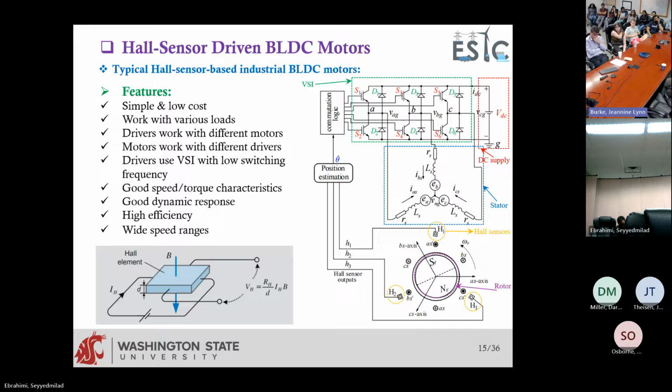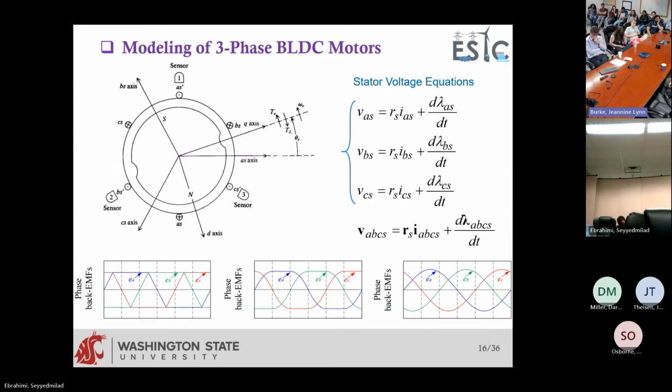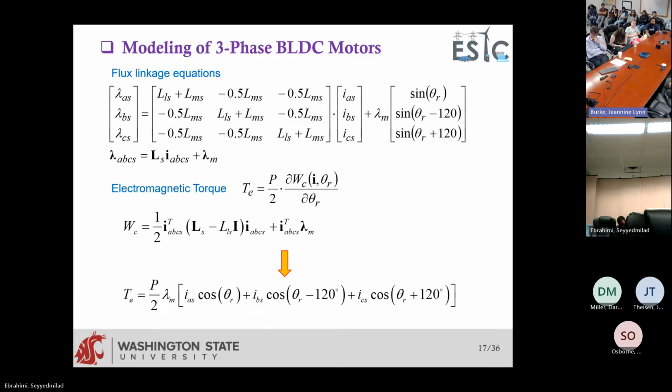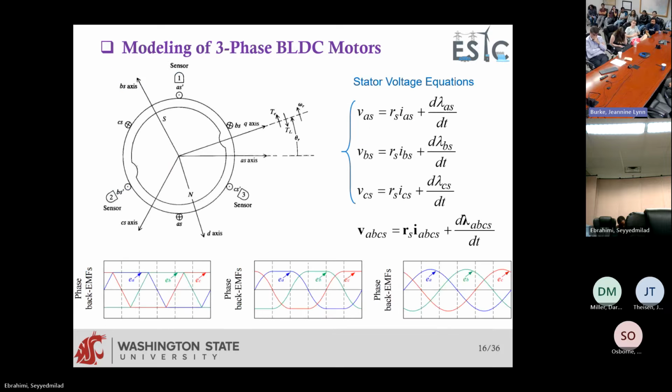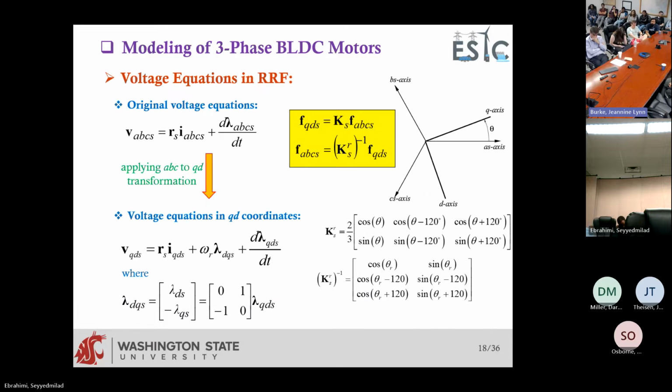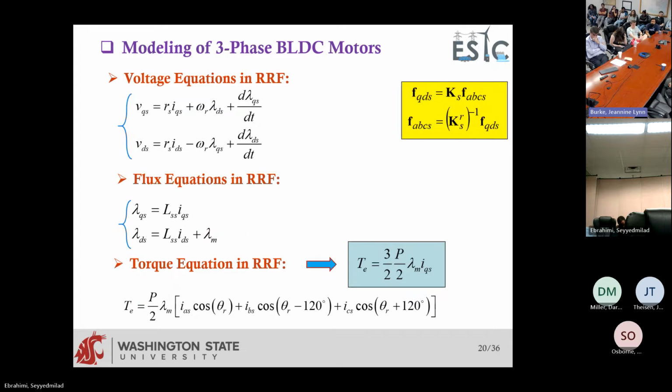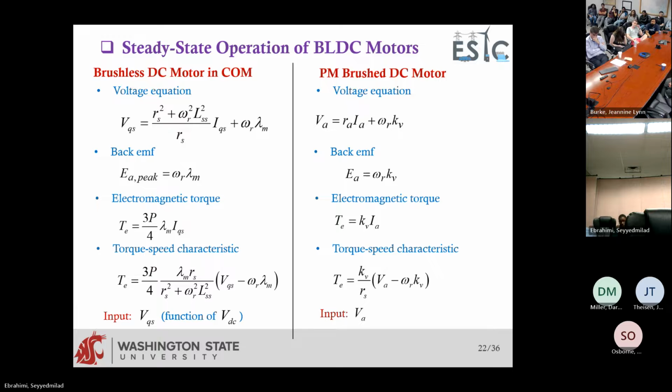Sorry, I missed that. So you mean to say when the source itself has harmonics, that's the reason? Or even if you use EA, EB, EC, can I assume they are sinusoidal themselves? You cannot assume. For modeling, you can say that they're sinusoidal. When we wanted to formulate, we said that they are sinusoidal, but in reality, they're not sinusoidal, they look like this.